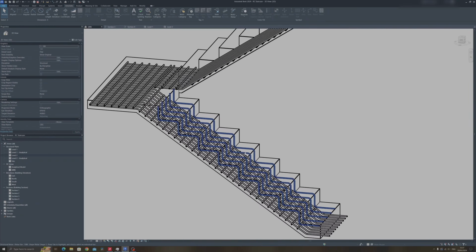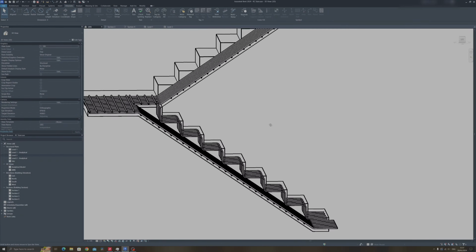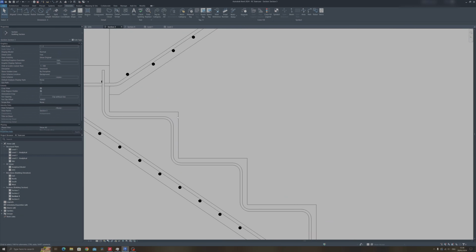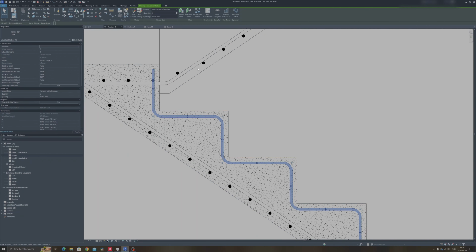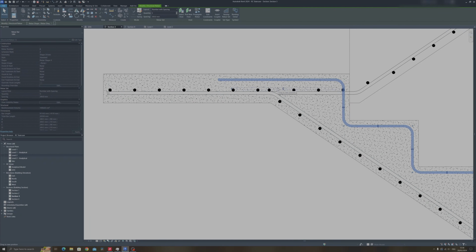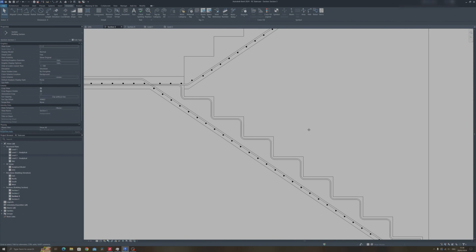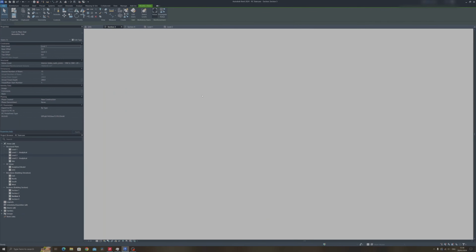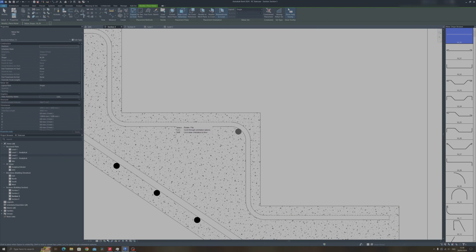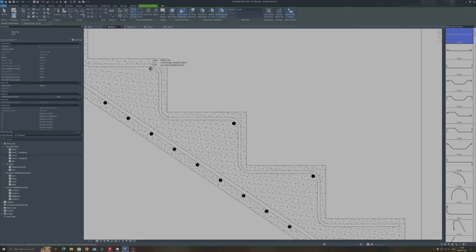So that's about enough. And usually for the nosing reinforcement, we have one rebar at least going into the staircase from this point of view. So that's quite simple. Let's just edit this one over here and draw it in like this. Okay, so now let's draw in the last bit of additional reinforcement for your nosing here. So we can just typically just put it in like this.